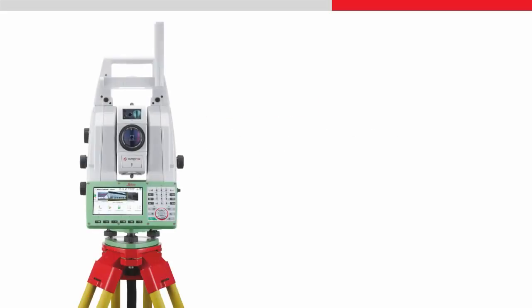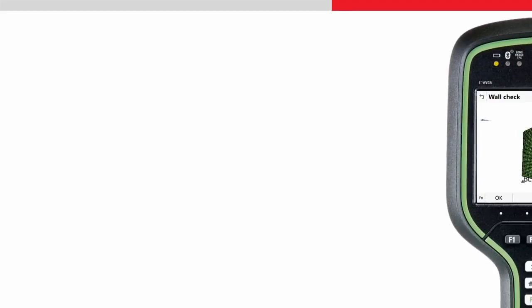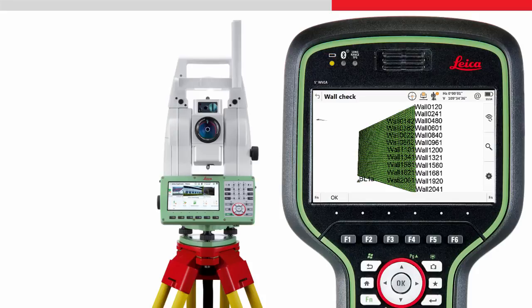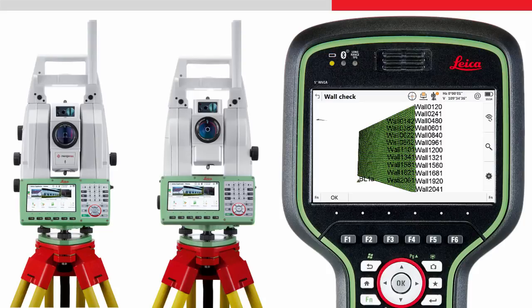For this task, we will not use multi-station scan data. We will use a grid of points which were measured using a TS16 total station. The Inspect Surface app is not only for multi-station scan data. It can be used with any total station data, but more data can be collected more quickly with a multi-station.